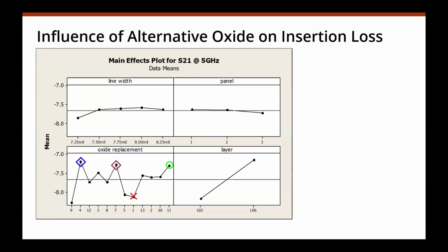Now, very important to mention, if you look at things like that, you may wonder why people have even used such poor oxide replacements. It needs to be clear, that's poor from a signal integrity, from a loss point of view. But there is, of course, typically an advantage of higher adhesion with more roughness. So you can't say in general that more roughness is bad because it increases losses. Reality is, if you want to go to lower insertion loss by going to lower roughness, there is going to be an effect on adhesion of different layers. So it's a balancing act in how far you want to push, how far you need to push the envelope. And there are still cases where a pretty standard oxide replacement is going to be a good choice because it gives you very good adhesion, even if the insertion loss is going to be higher.